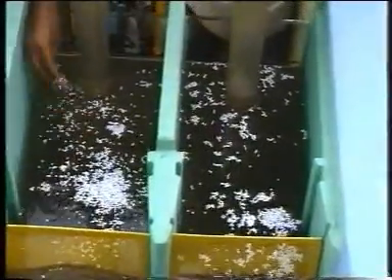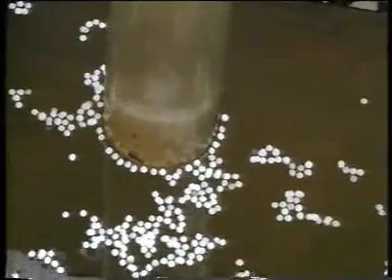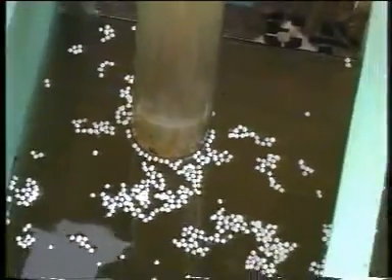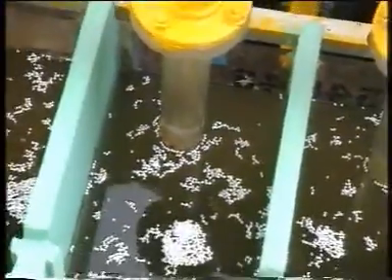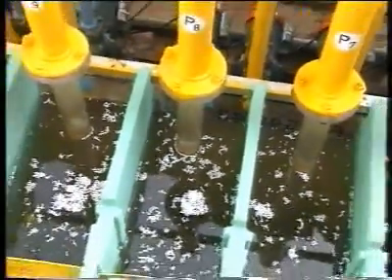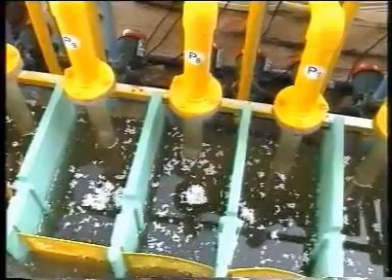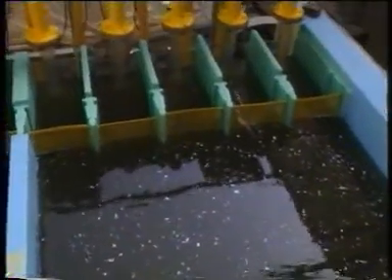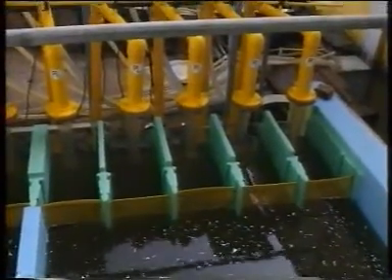The paper confetti is used to trace the path of the fluid particles and to locate stagnation zone, if any, and surface vortices. The tests were conducted at 2F conditions, in other words, twice the normal discharge, to check for the possibility of the formation of surface and subsurface vortices in the pump chamber.